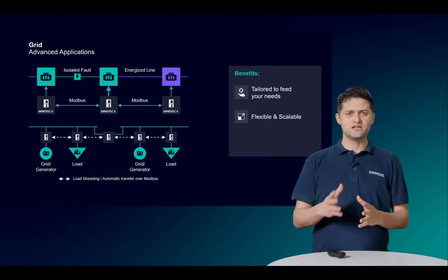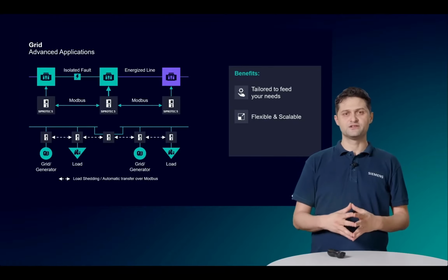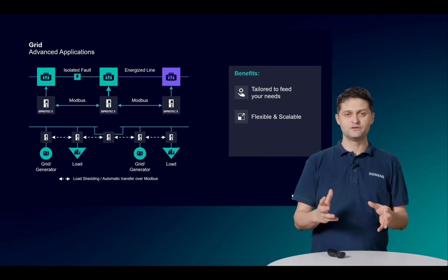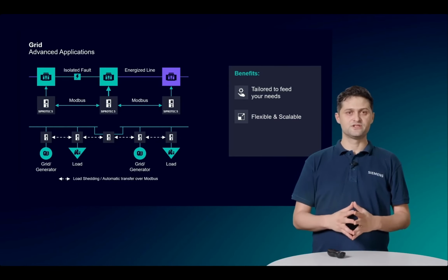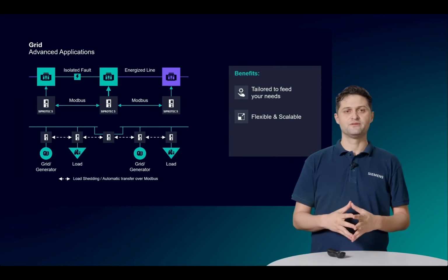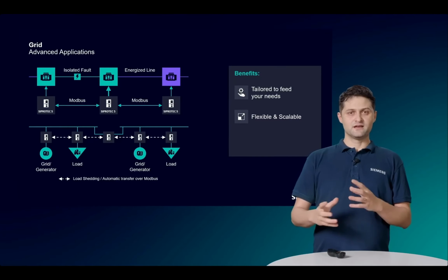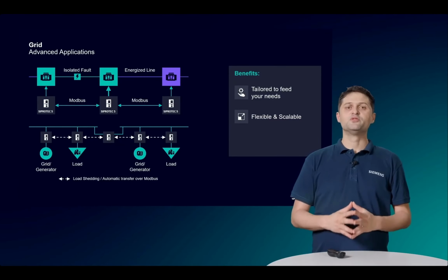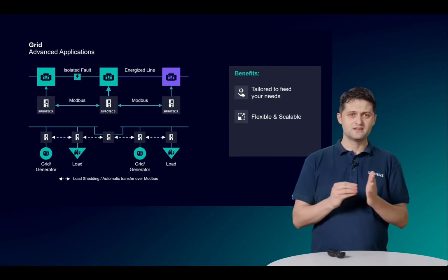Whenever the source changes, the substation should open or close the necessary circuit breakers without disturbing the energy flow to the load. Such an automatic transfer switch scheme is also achieved with the Modbus client server feature in SIPROTEC 5. Unlike dedicated ATS devices, with the SIPROTEC 5 Modbus feature, you can have a highly customizable solution fitting your exact needs.